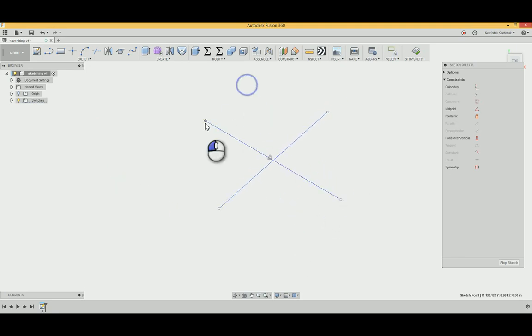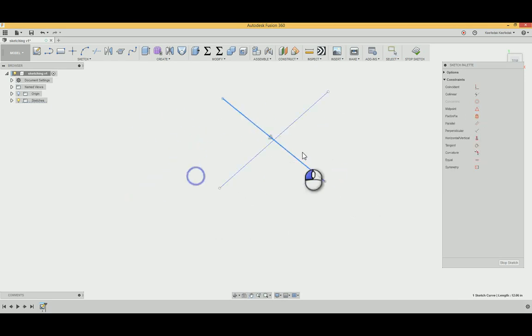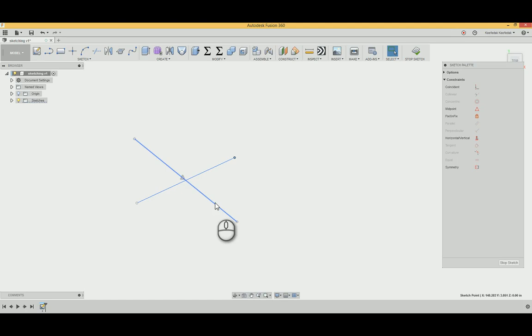Okay, so well then that's good. That brings us to the next constraint, because do you notice this thing just kind of floats around in free space when you're sketching, and we're going to see this pretty soon when we move on to modeling something. Notice the lines are blue. That means that those lines are not what we call fully constrained.